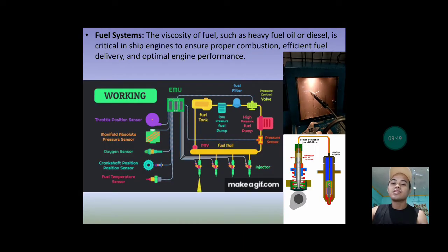If the viscosity of the fuel is at the right reading, for example, most ships have 15 centistoke of fuel viscosity on the system, following the manufacturer's manual and its recommendation, then the lower the viscosity, the better the atomization of fuel, the penetration of fuel, and the combustion of fuel will be more efficient, and the engine performance will be at its optimum performance.